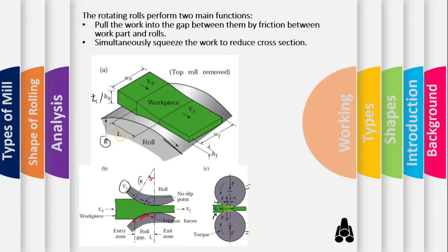And as we know, the metal flow is continuous, there's a continuous flow of metal between the rolls, so this change in velocity of the workpiece before and after occurs gradually, right? It was lower before, and it is higher than the roll speed after passing through.